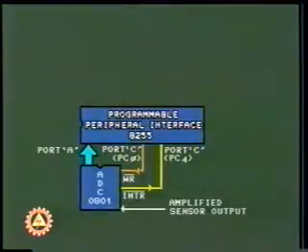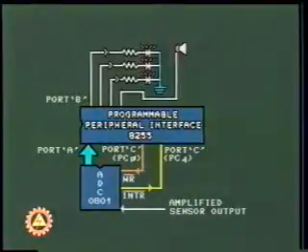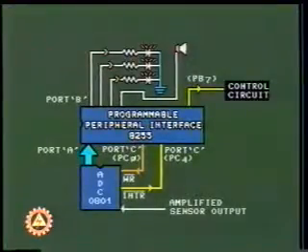Port B of the 8255 is used in output mode for generating audio and visual indications regarding the status of the system. However, the PB7 line is dedicated to firing the control circuit for pouring chemical into the process.